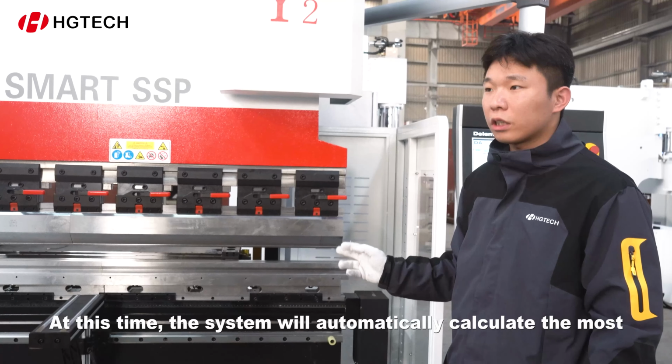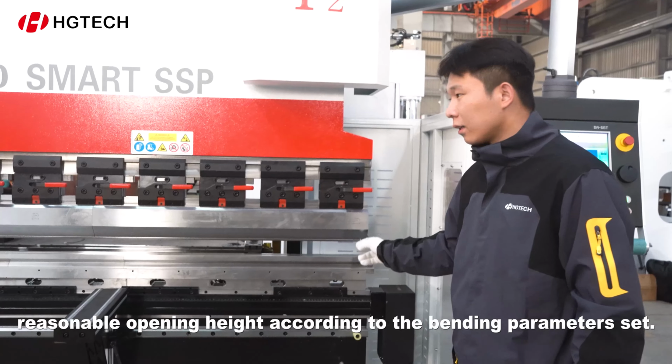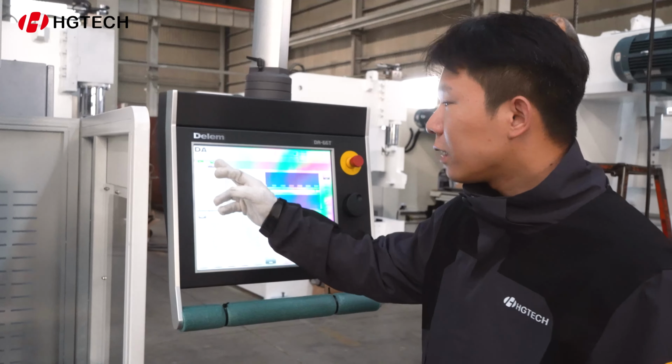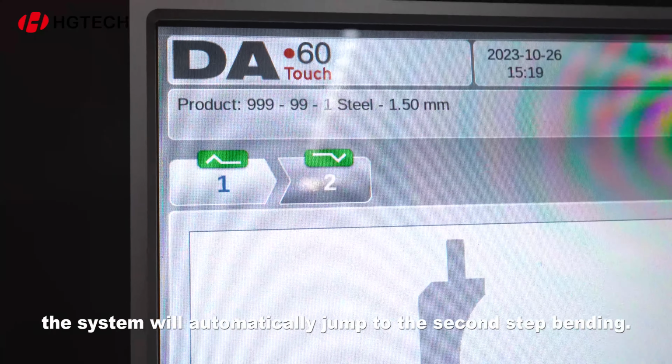At this time, the system will automatically calculate the most reasonable opening height according to the bending parameters set. This advantage is that it can speed up production. Just perform the first step bending. The system will automatically jump to the second step bending.